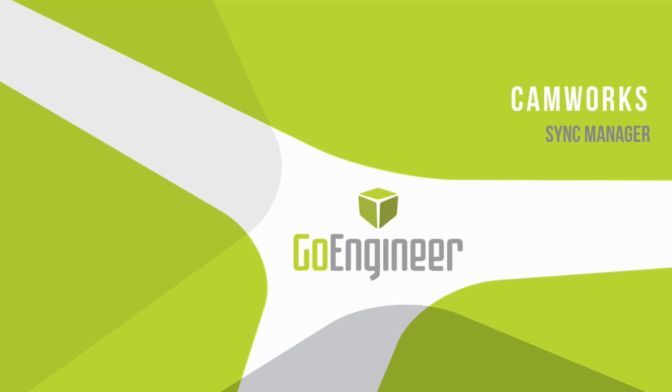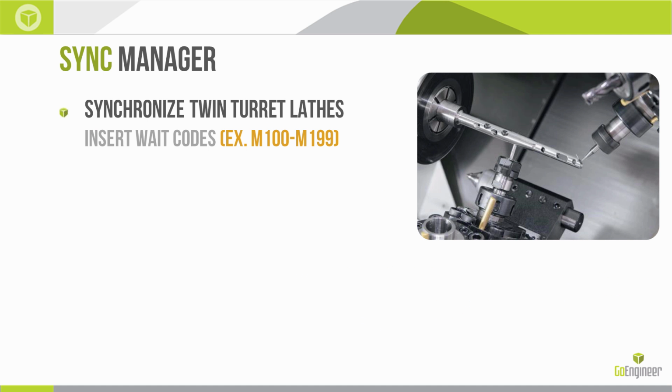So the CAMWorks Sync Manager, what is it? It's a module for CAMWorks that allows us to program twin turret lathes. Twin turret lathes, normally a front and a rear turret, like the image that you see up there, are becoming more popular today. A lot of times these lathes have live tooling or just some regular turn tools on them. But programming them adds some extra steps to the process and extra codes that we need in the G-code in order for them to function correctly.